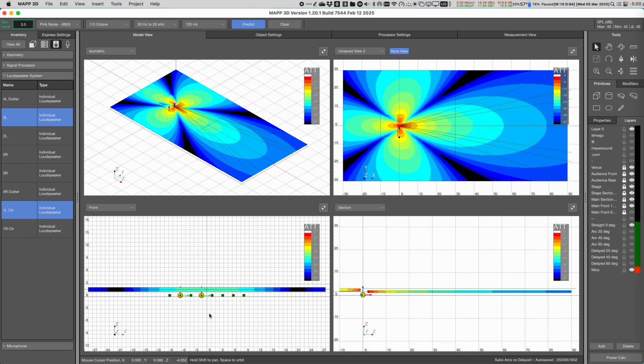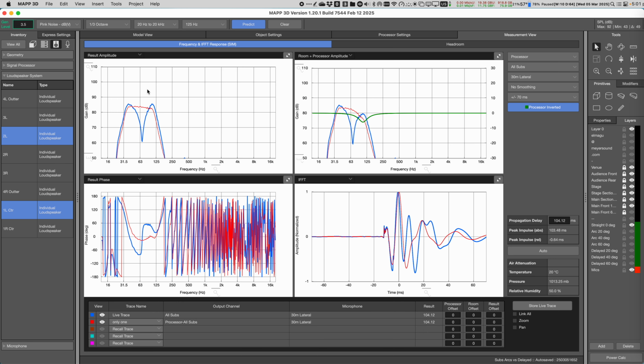But if we select two lateral speakers side by side, in this case number 1 and number 2, now you can see this lateral cancellation. And important to understand, in the comb filter, at twice the frequency, around here, we have 6 decibels more than an individual speaker. However, in this case this is outside the bandwidth, so this is beyond the low pass filter.